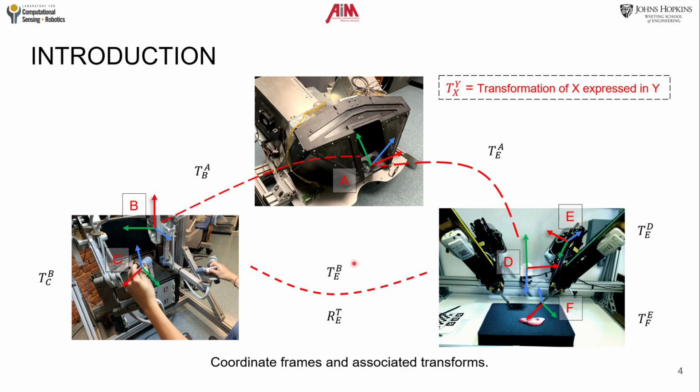As shown in the image, coordinate frames are assigned to the input device's base and tip, the heads-up display, the remote camera, and the remote robot's base and its end effector. With this arrangement, one would require two additional transformation matrices to align the linear and angular mapping of the input device with the remote end effector. These two matrices are convoluted as they are affected by all the higher-up components in the hierarchy.